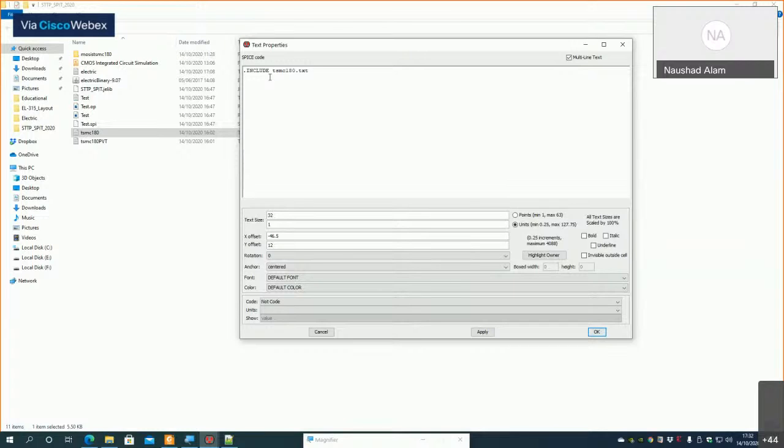After that, I will add VDD. I will add some parameter, for example, .param supply is equal to 1.8 volt. This parameterizes it, and we can change the supply voltage just by changing the value here. That is why I am using this .param command. Then I can use VDD, and the nodes are VDD and ground 0 DC, and then I can simply write supply.